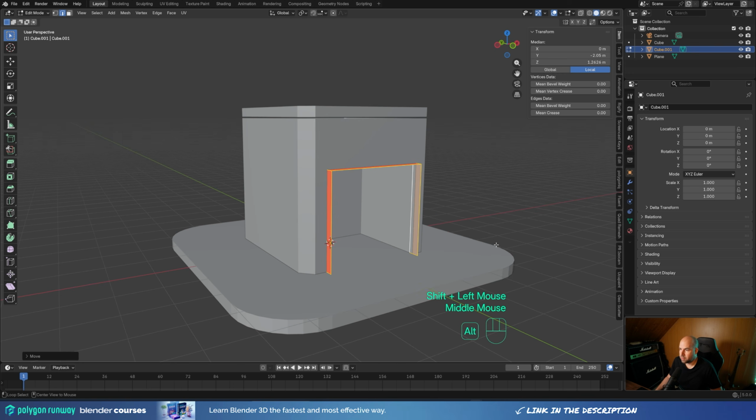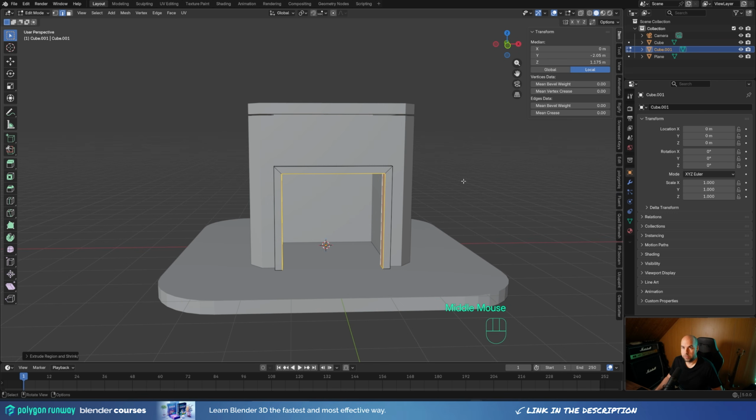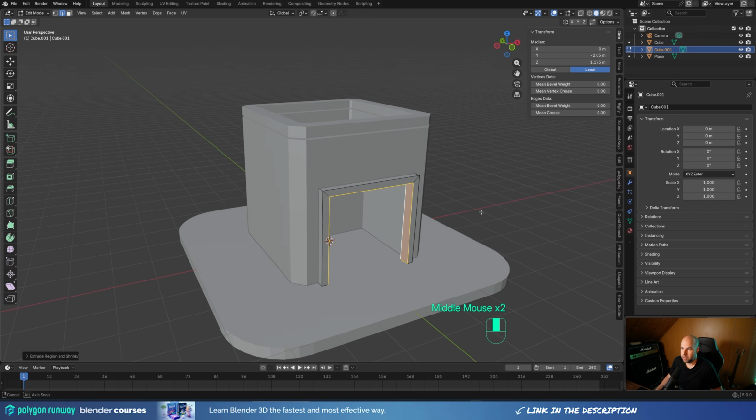And now we can press Alt E to extrude along normals. Let's just select this option and it will enable extrusion this way, but you can see it skews a little bit as you go inside. So you can enable even thickness by pressing S, and down here underneath the timeline you will see as I hit the S, it highlights that that function of the extrusion is enabled, and you will see how the geometry changes. So let's do something like this. And now nothing is red, so we don't need to flip any normals, we can just continue the modeling.